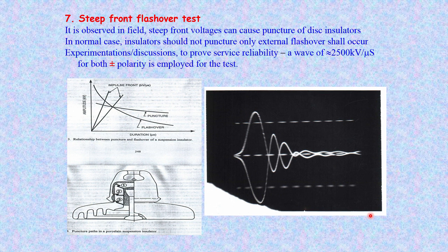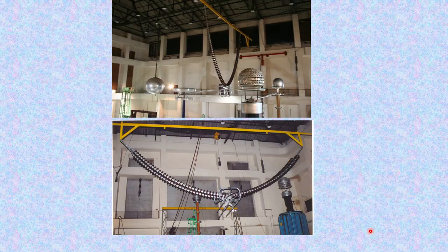So, voltage distribution is very important, to see whether the potential is properly distributed across each insulator in the entire string. In the line end here, the first 3 insulators are shielded by a corona control ring, and in case proper shielding or proper grading is not done, the insulators near the line end, 1, 2, 3 or 4 insulators, could see more stress compared to the ground end or the insulators at the middle, which in the longer run in the field could shatter, and the voltage distribution could be disturbed.